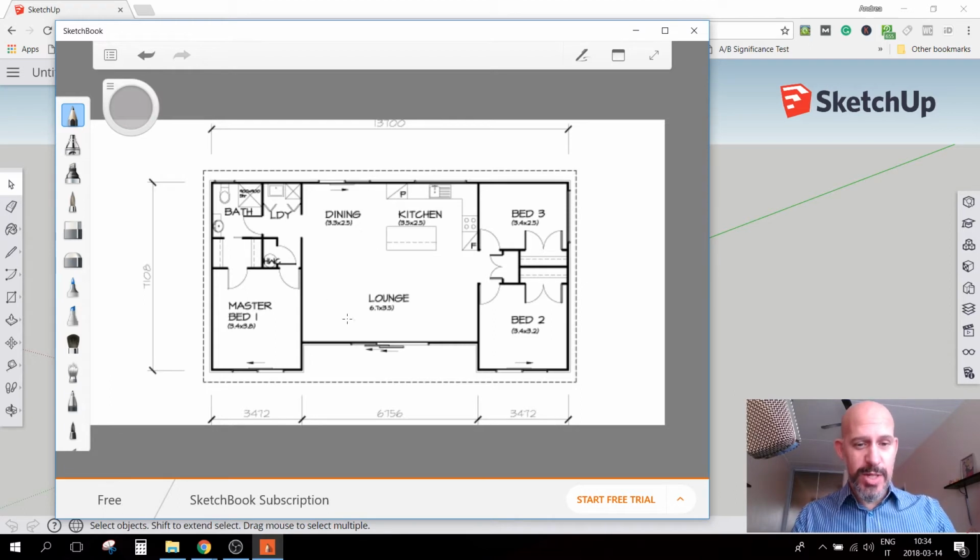And so if I have to start to draw this, man, I wouldn't use this 13700 because you see that you are going to miss like half meter from the width because the walls are too thin. So a way to start drawing this and make it properly is to take the center room. So this 6.7, this is the internal space of the lounge, and 3.5 meters is the width, and then I have 2.5 meters. So the entire room should be 6.7 by